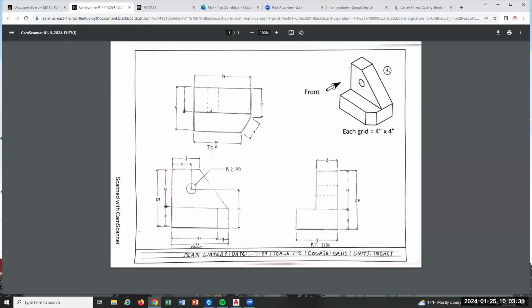Actually, manually, it helps you too, because all of the geometries from the front view project up and create something in the top view, right? So the hole should project straight up and create hidden lines up here. It does, but it's a little bit shifted. That was extra work to not put it in projection, right?